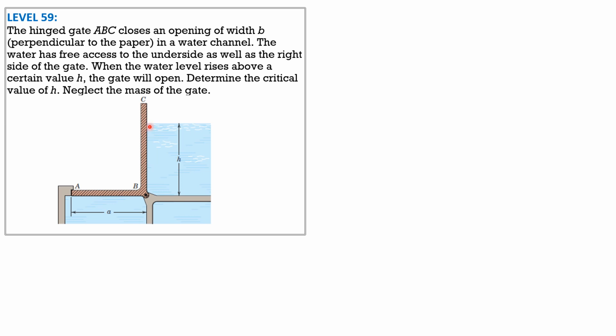And here it's from 0 to maximum at B, where the maximum pressure is gamma times H, the same as here, specific weight of water times H. So for the solution, that's the pressure diagram here, triangular, and this is specific weight of water times H. Let's call the force F or F1, and this distance is 1/3 of H as shown.